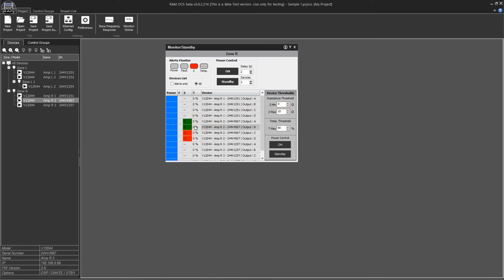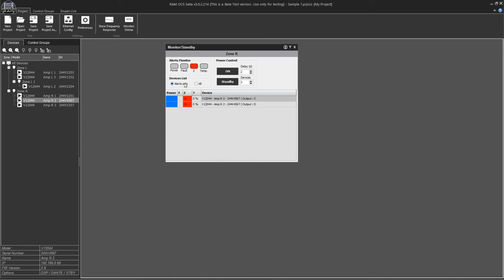We need to take into account that the impedance measurement of any speaker is something essentially variable depending on the musical program, so big impedance fluctuations are to be expected. The impedance measurement shown is the average of the minimum impedance measurements being monitored, to try to attain a value similar to that of the nominal impedance value of the speaker. We need to note also that in order to obtain a correct measurement of impedance, we need a minimum output signal to be able to carry out a precise reading.